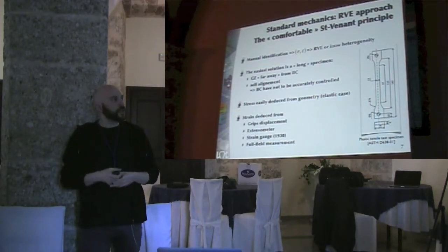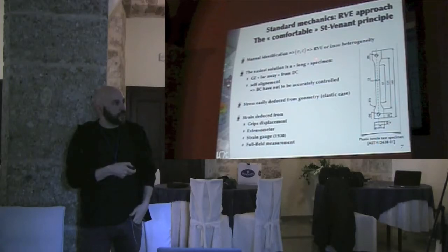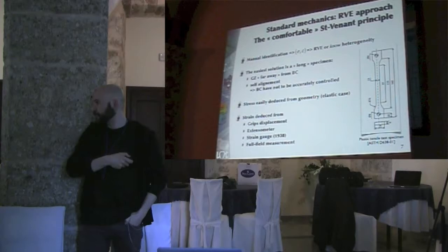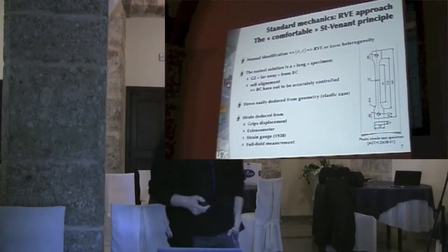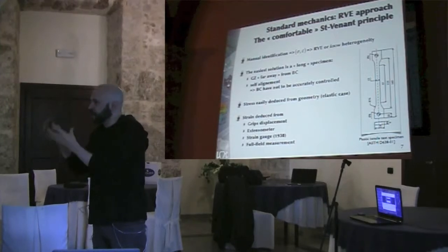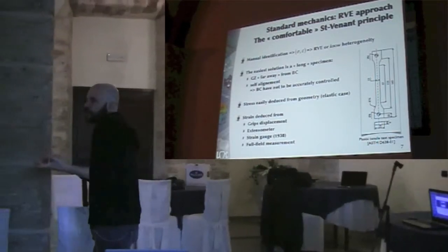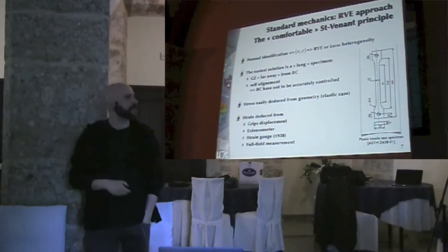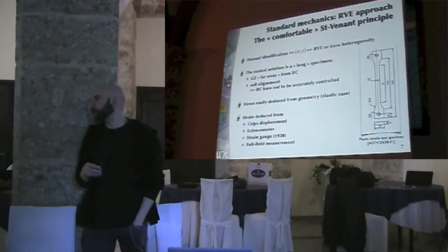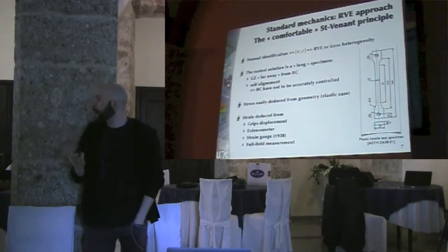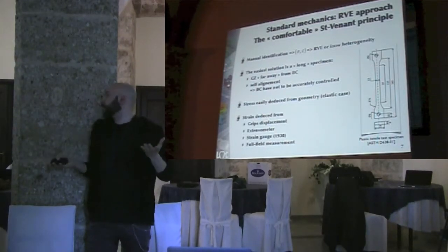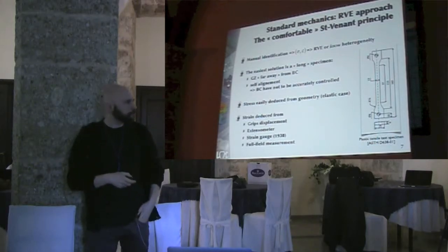So to do that, it's interesting to use a representative volume element, okay? This is due to Buffon. Buffon was the first one to say that you have to have a sort of specimen that averages the microstructure, in fact. He was studying wood pieces. Or you can have a very well-known heterogeneity, like in elastic bending. But otherwise, you've got heterogeneities and you can say nothing about your experiment results.